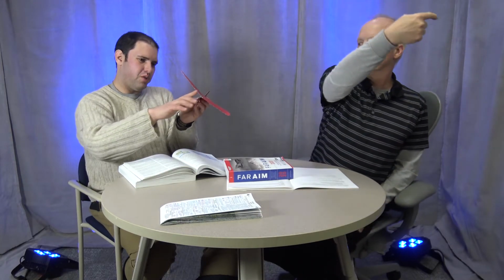And besides, in a car, when you go around an on-ramp or an off-ramp on the highway, you know how you feel pulled to the outside? Well, you'd feel the same thing in an airplane if you tried to turn without banking. So what we do is we bank the wings, and that does two things. First of all, that directs some of the lift from the wings sideways to help the airplane change direction, so that lift is pushing toward the inside of the turn. And then it also makes it more comfortable for the passengers because you're not feeling pulled to the left or the right in the turn.